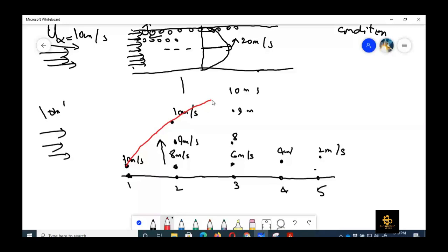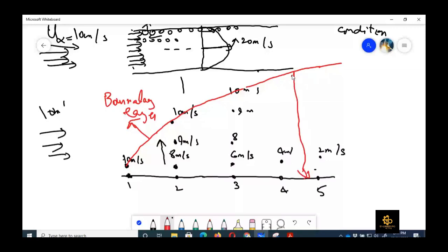This edge is called the boundary layer. The boundary layer thickness is the distance away from the surface at which the value of the velocity becomes almost equal to the free stream value coming from outside the pipe. We represent it with a simple delta, and we would also discuss it again in chapter number 8. Delta is a function of x, and we can easily see that this boundary layer is growing in the x direction as the flow happens.